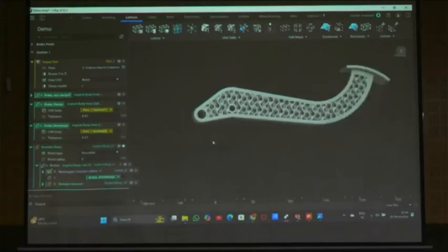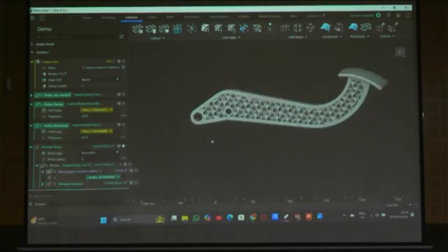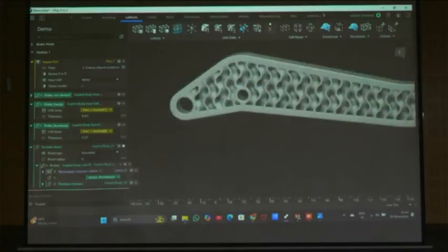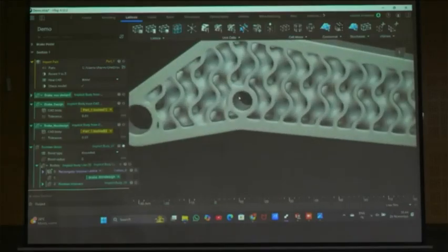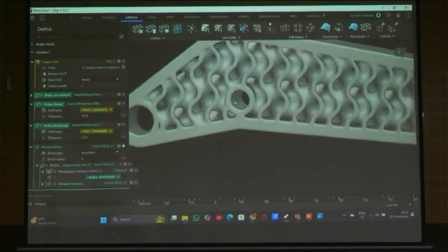Okay, now we are getting the final design, right? We can preserve the holes and all those things. The main thing is how to identify the design and non-design regions. The terminology is the same for generative, lattice, and topology optimization. The main thing is the preserved region and non-preserved region. Non-preserved means design space, and preserved means non-design space.